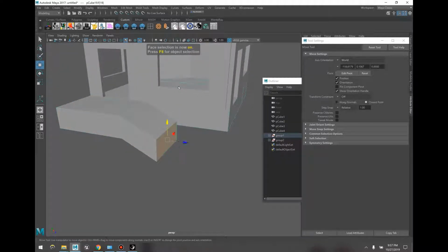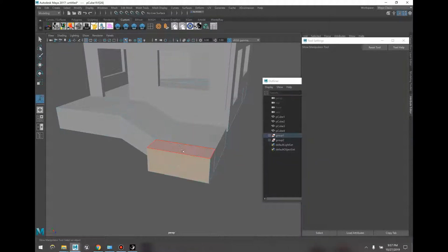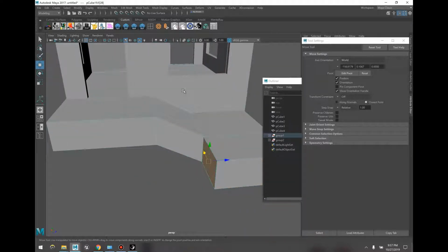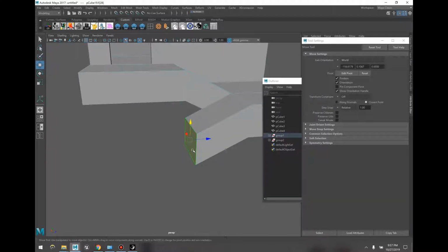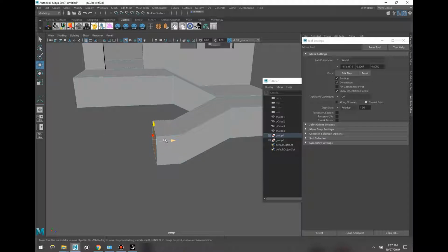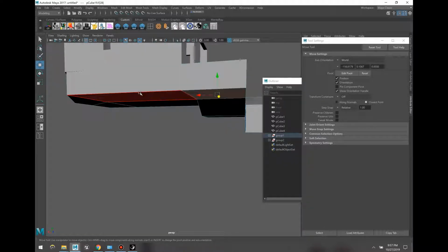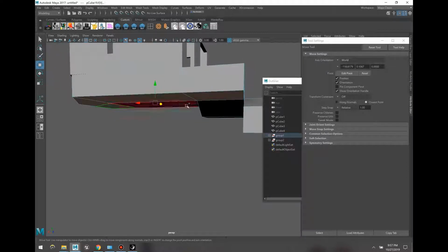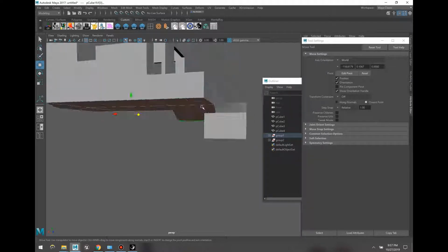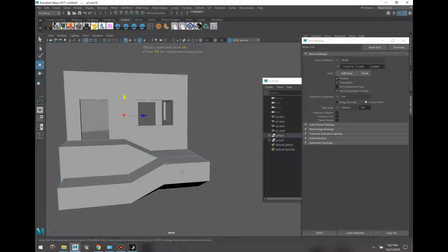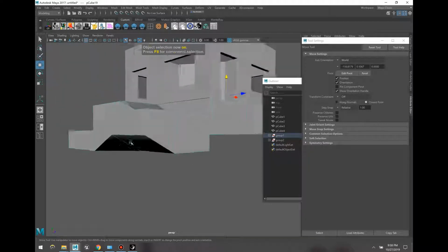And then if I'm getting even more complex, I can go like this, and then very quickly I can build the stairs. 1, 2. So this is, yeah, that's when I like to do extrude. And then what I can do is I can select all the faces like so, and then pull that down, and we get a nice ramped thing here. So you'll see, hey, this is kind of off.